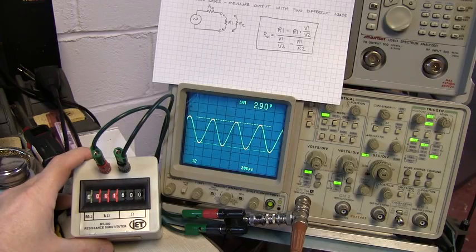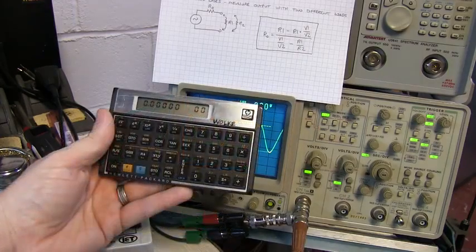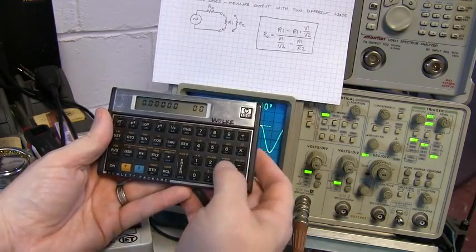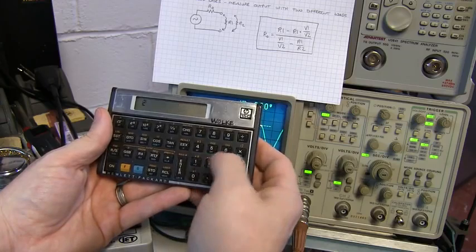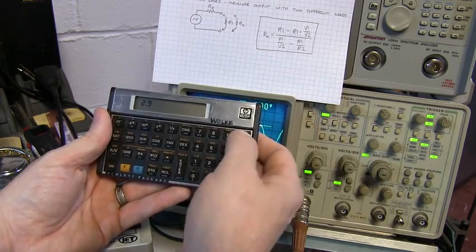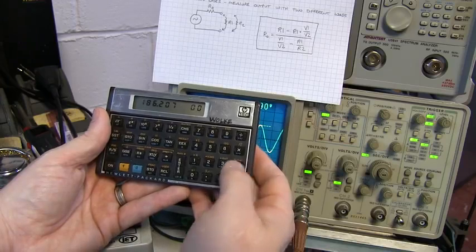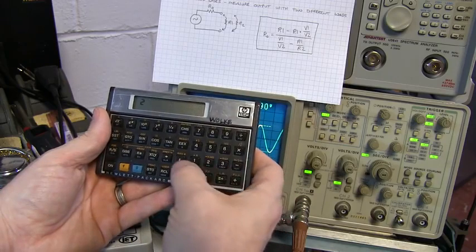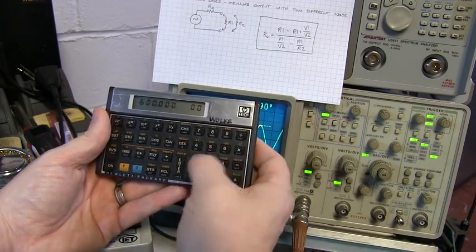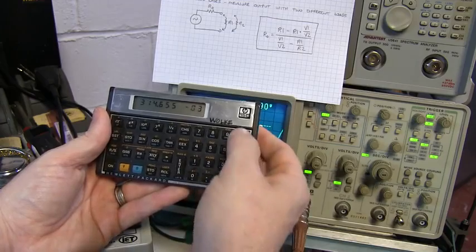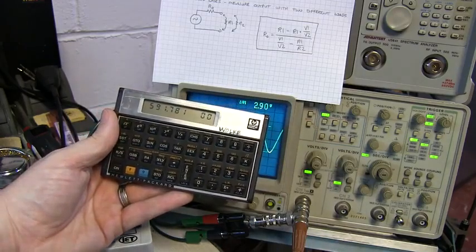So we can use those 2 values, 2 volts at 600 ohms, and 2.9 volts at 1600 ohms, and calculate the output impedance from that. Okay, we'll go calculate with those values. So R1 was 600 ohms. I'll enter that in here again and multiply by 2 volts, divide by 2.9, and subtract that from the original 600. And I'm also going to take 2 volts divided by 2.9, and then my 600 divided by 1600, subtract that, multiply. I'm left with about 592 ohms.